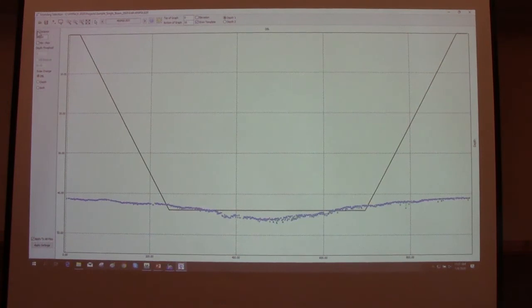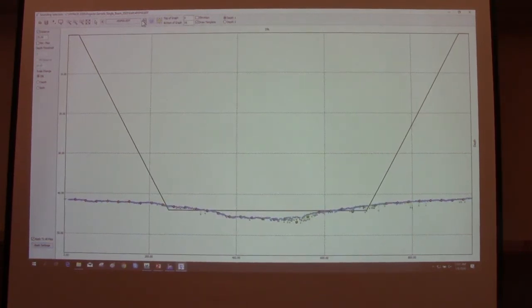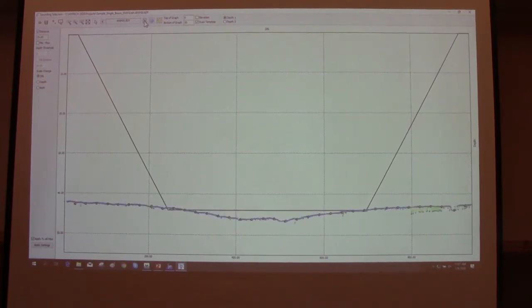I'll set my distance. I'll leave it set to 25 feet. So what I could do is go down here. It gives me the option to apply this to just one file, or if I check the box, it'll apply to my entire data set. So I click on Apply Settings. It's going to highlight. You'll see it highlighted in red along the screen here. And it chooses that. So if I scroll through my files, you can kind of get an idea of which ones are going to be selected and saved.